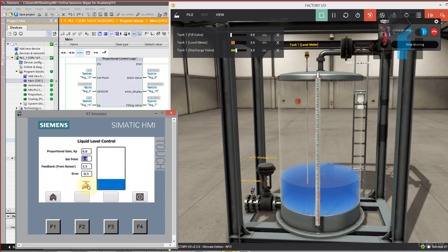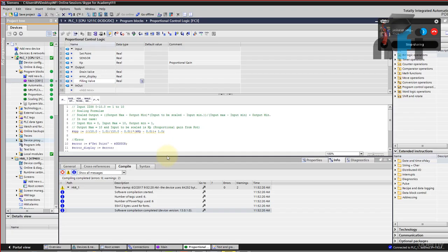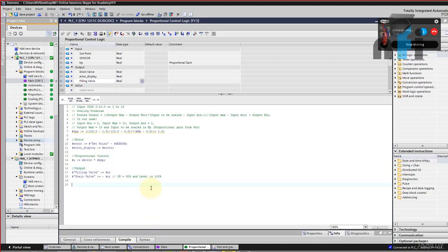So how to avoid that? We have to write the limits in our program. Okay, the limit says when the value of the valve is more than 10, the valve should have the value 10. The maximum limit of the valve should be 10. Similarly, the minimum limit should be 0. Okay, so to define these limits, it's a little bit of an if and else statement. I will write here limits. It's easy, but it's a bit of work.